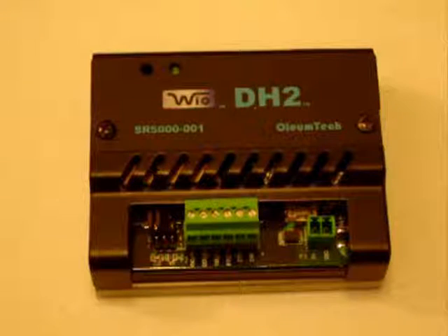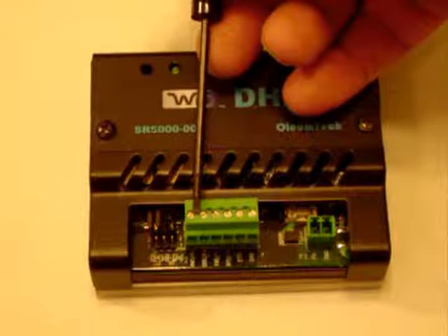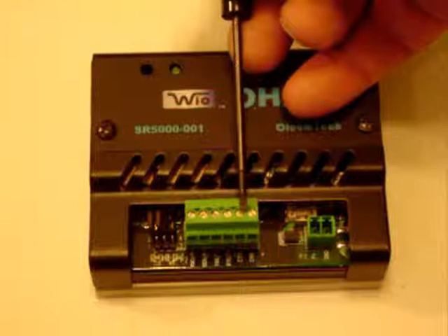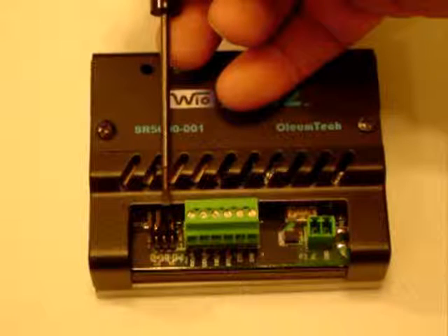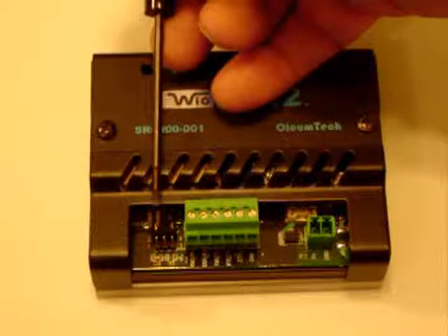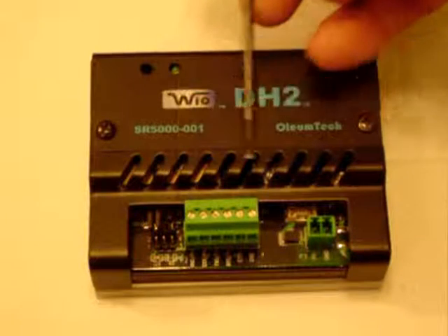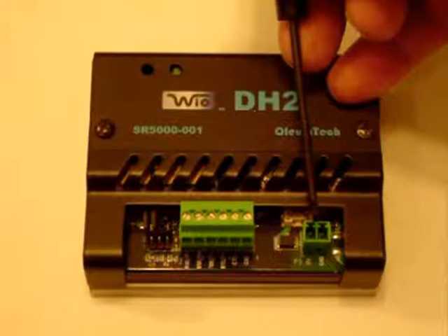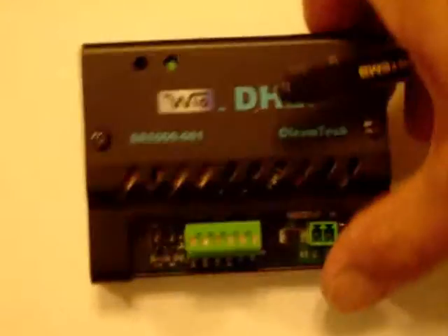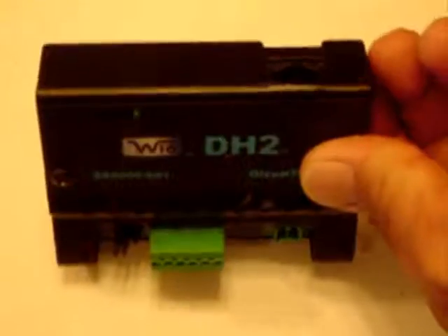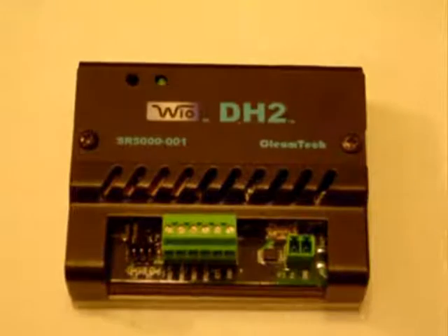For the DH2 connections, you have a 6-pin Phoenix connector in the front for 232 or 485 communication wiring. The jumpers next to the Phoenix connector should be installed if using RS-485. You also have wiring for power and ground. The connectivity port on the back of the DH2 is where you would download your Breeze configuration. You also have the MMCX connector on the side for antenna connection. And that is all of the connection capability of the DH2.